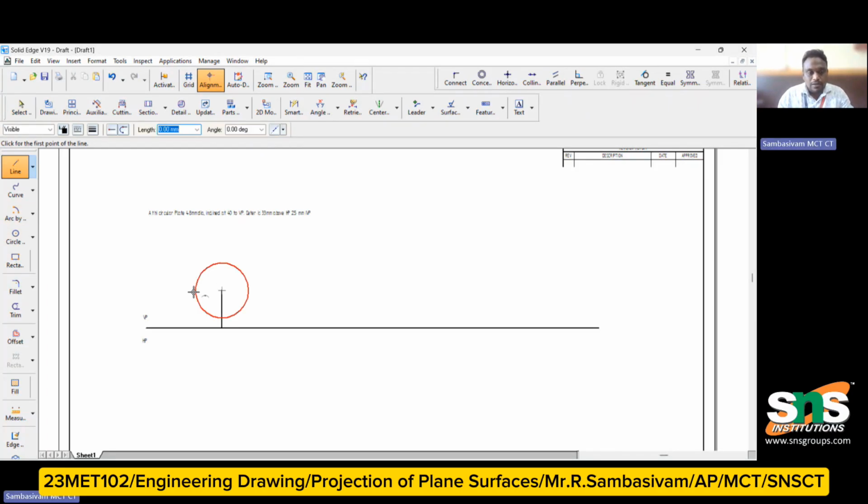Similarly, from this point, I have to make the line for the trace. I have to make the trace line, joining like this. From this point, I have to take the distance: the question says 25 mm in front of VP. So I have to draw the 25 mm from VP. These lines ought to be reference lines.